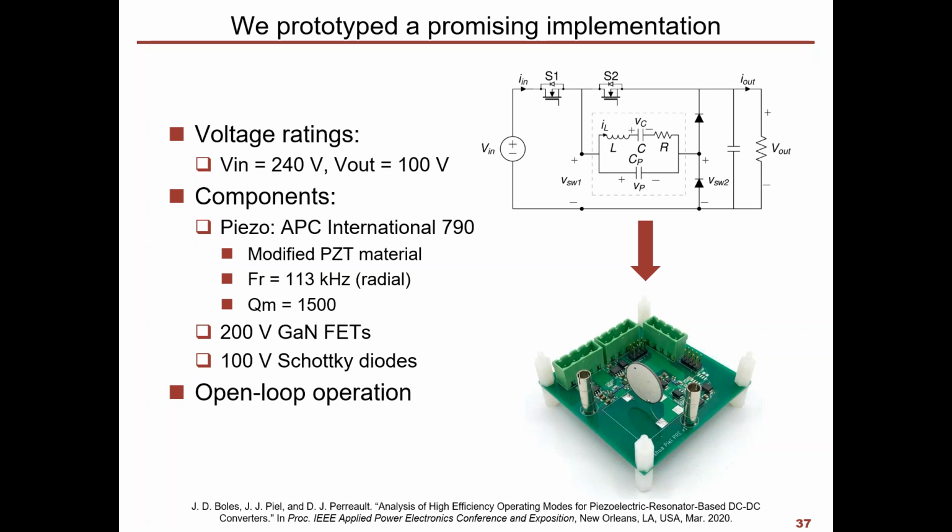We don't have that problem with inductors and capacitors, and so in a typical resonant converter, you can see we've got many 50-50 duty cycle, constant duty cycle converters. Those are much simpler because the magnetic component in those converters can handle instantaneous voltage changes, while the capacitance in this piezo cannot. So I would not recommend these switching sequences with just inductors and capacitors.